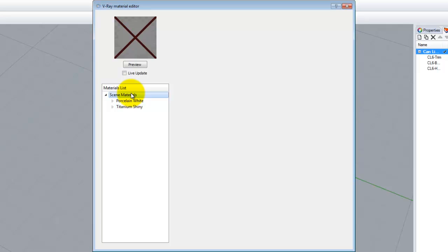Does that make sense? If you look at a light bulb, you see the light bulb. In reality, in our world, that light bulb is providing the illumination, but you can also see it. In V-Ray, a light source is invisible. We can't see where the light's coming from, but it starts at a point and casts the light. So we need to mimic what the light bulb looks like. And we're going to use a special type of material that's called an emissive material to do this.